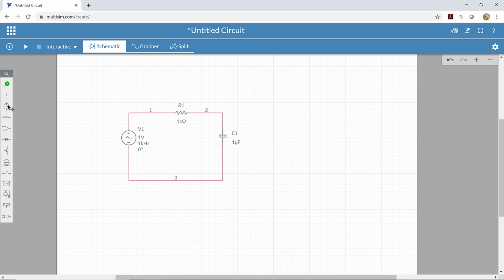So that means that I want this low-pass filter to cut off everything above 1000 Hz. Okay? And I want the high-pass filter to cut off everything below 100 Hz. So what we can do is, right now, we can set up this low-pass filter and make sure that it cuts off everything above 1000 Hz before we go on and finish making our bandpass filter. So let's do that. Let's do a little bit of math and figure out how that's going to work.